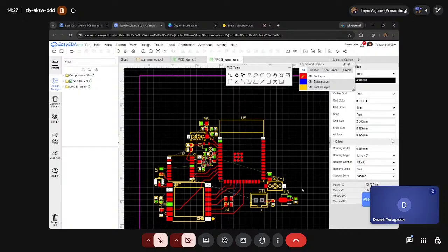So what we'll do is we'll have a ground plane beneath the signal trace so that the loop area becomes small. And even though the forward current path may be considerable, the width of the loop may be small so that the total area is small, and the radiation or the noise from the circuit is less. It doesn't radiate as an antenna structure.